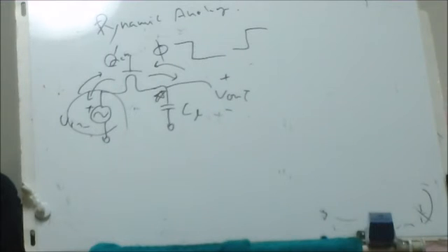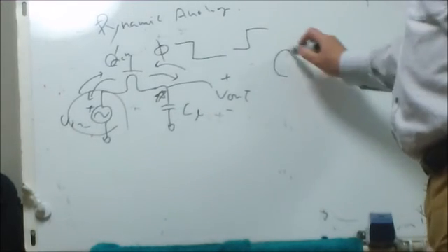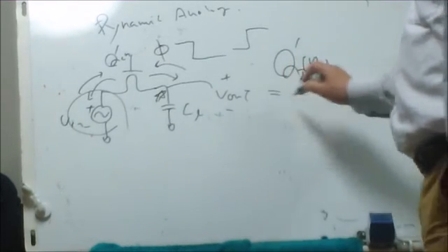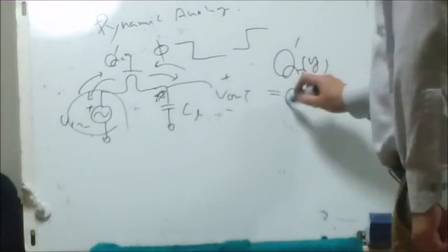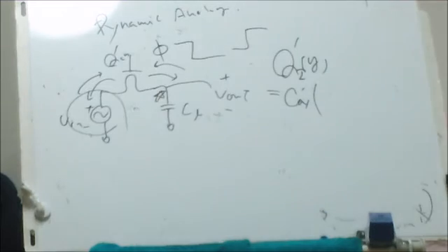Although the charge injection mechanism is itself a complex one, many studies have sought to characterize and minimize its effects. It has been shown that if the clock signal turns off so fast, the channel charge distributes fairly equally between the adjacent nodes. Thus, half of the channel charge is distributed onto C load. From chapter 6, the charge per unit area of an inverted channel, the inversion layer, can be approximated as Cox prime times VGS minus VTHN.